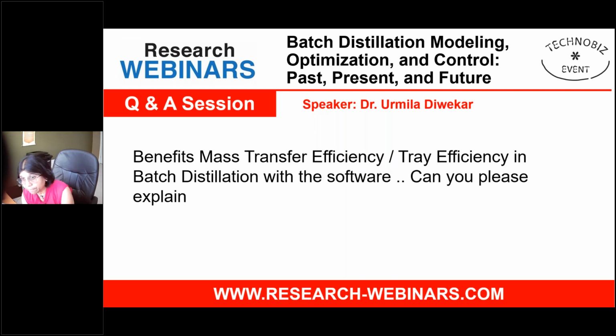Mass transfer efficiency and tray efficiency. Most of the models in the literature, as well as in the software for batch distillation, don't consider tray efficiency as inherent in the model. They implement it separately because you have to write differential equations for theoretical stages. So it operates similar to continuous distillation, and there is an efficiency package which will calculate the efficiency for your column and iterate on it, but it's not inherent in the model itself.